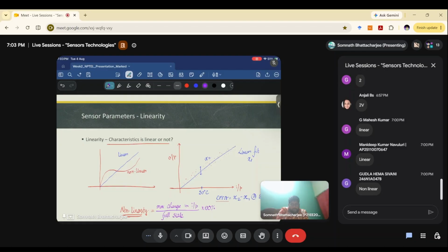So let's say if a gas sensor is not very selective, what it can do is that while looking for NH3 gas, that is ammonia gas, it's also getting activated by nitrogen in common air. So it will be a faulty device, right? So we need a completely selective device which can detect only a single parameter and not the other parameters. So then we would say that this is the NH3 sensor, right?